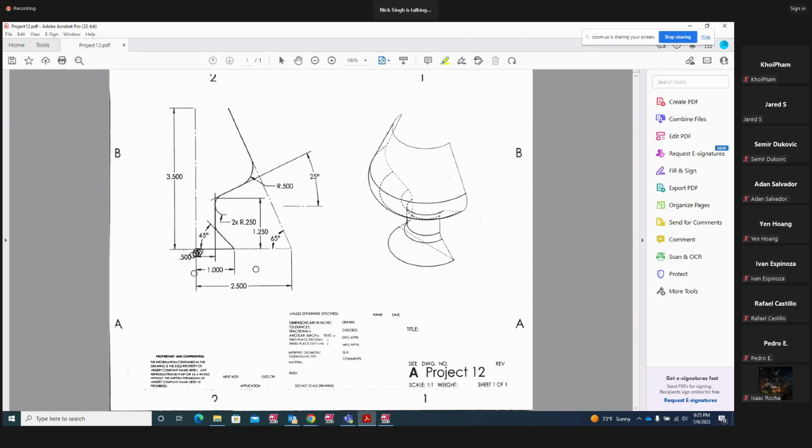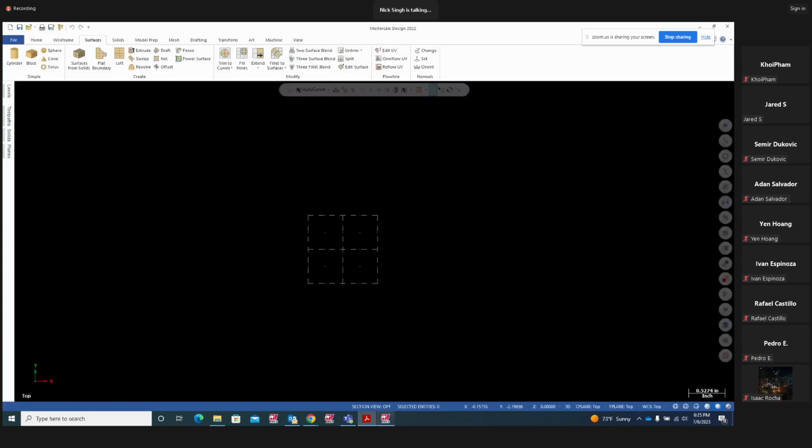We're going to create a 1 inch line first. Then at the end point, we're going to create a line at an angle of 45 degrees. Then we can create a horizontal line, vertical line here, sorry. And then we're going to create this line over here, starting at 2.5, x y 0, and that angle line is going to be a 65-degree angle. Okay, so let's start from the origin, create that 1 inch line first on the construction plane top.